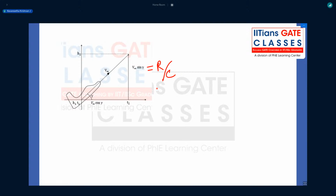Okay. So, what is rate of climb? In some textbooks, they represent rate of climb by V suffix c. It is nothing but dh by dt, the change of altitude with respect to time. So, it is the total altitude gain for a given time.